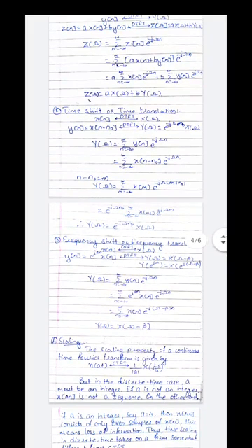We can combine both the exponentials inside the summation and rewrite it as summation n minus infinity to plus infinity x of n e to the power minus j omega minus beta of n. So this is the definition of the Fourier transform for the frequency omega minus beta. So the spectrum Y of omega is X of omega minus beta.